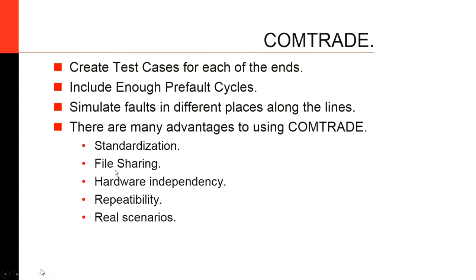As long as your relay test set has the ability to play back those files, then you can use any relay test set to play them back. For example, if there was a fault in the system and the fault got recorded in a relay or some sort of recorder, you can play it back in the relay and see if it operated properly, and if it didn't, why did it happen.